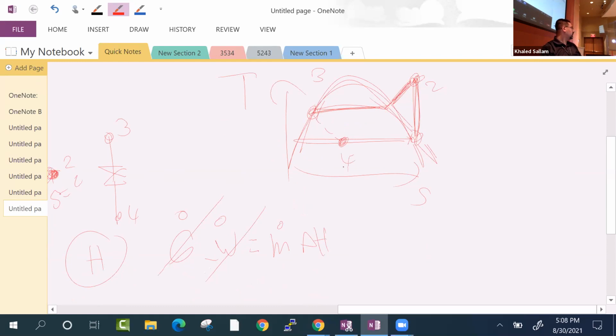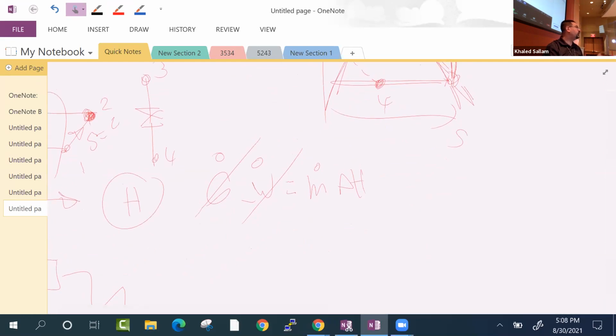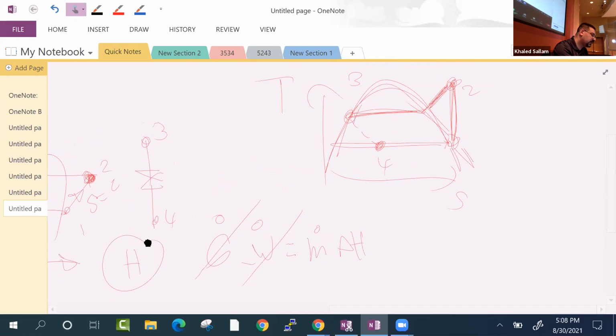That's called throttling. On a T-S diagram, obviously it's not isentropic. The entropy is not constant. Why? Where are the losses? So that's adiabatic and it's a small pipe. Well, tons of friction. And look at the loss of availability. You had this high temperature and pressure and you dropped to a very low pressure, right? So it's tons of irreversibility, huh? But it does the job. It does the job of what? Dropping the temperature. That's what we wanted, so that 4 is now ready to go to the cold side.